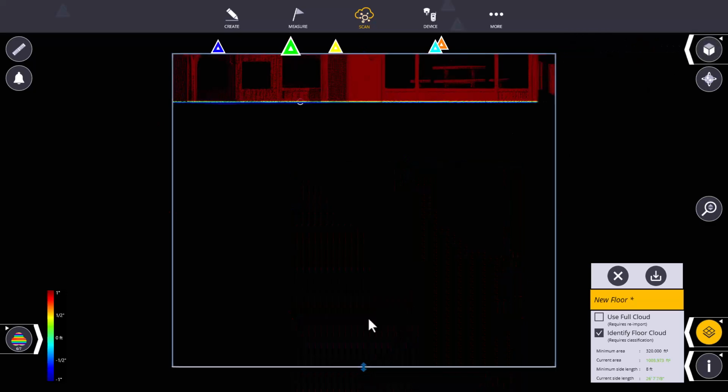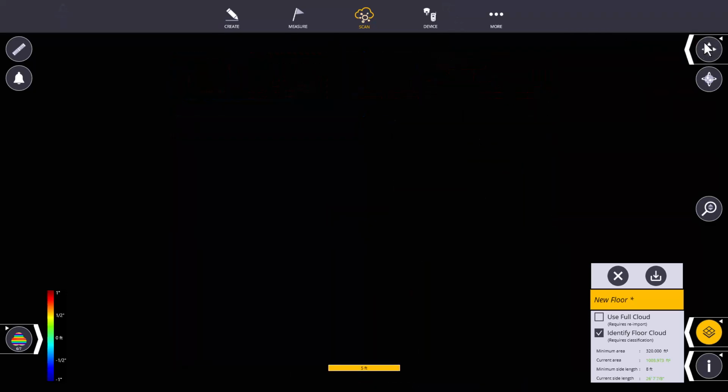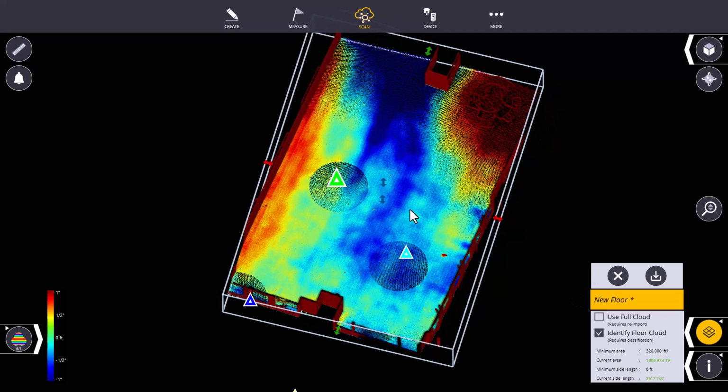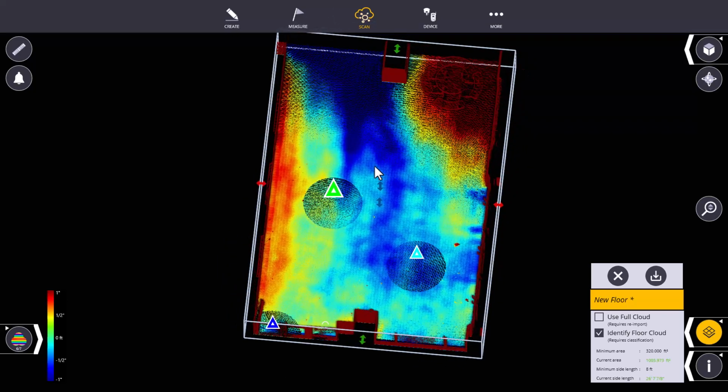And then all I'm doing here is dragging it around to make sure. So this is about 1,000 square feet. Definitely would probably want to come from here over. And how much area am I going to need to raise to make sure it slopes away? That's going to be the question. How much is high? I can probably ignore this area. I want to work on anything that's below in blue here to slope away. So that's 1,000 square foot.